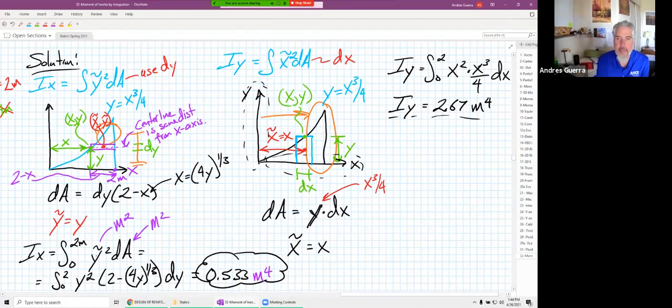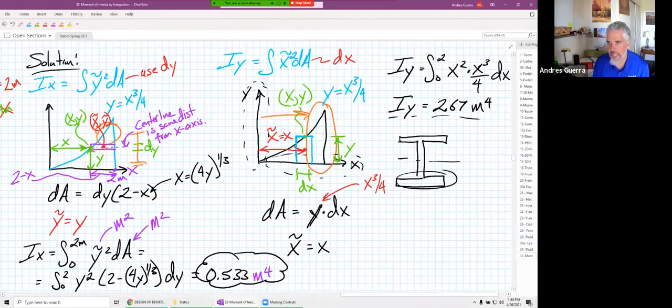So just to relate that back to where we started today's discussion about it being the geometric part of bending stiffness, just like those I shapes. When I showed you those pictures of those I shapes, you get all this area down here and down here that's really far away from that axis. That's a really large moment of inertia, and larger moments of inertia means it's stiffer. You're going to get less deflection, less bending. And by bending, I mean the actual bending deflection that's occurring, like when I show you the yardstick bending.